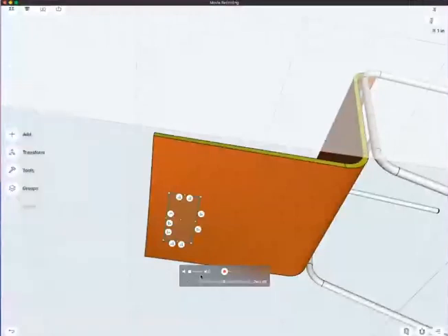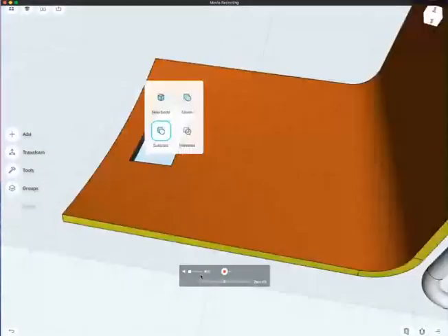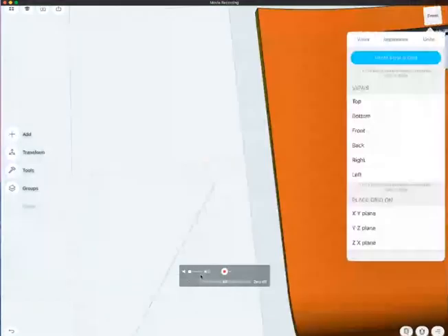Okay, so let's go to tools, and then actually, sorry, not tools. I can just select this face and then with the pencil extrude up, and it creates a cut automatically. See, it's a very smart tool. I can make a new body, I can join it, I can intersect or subtract it. Okay, good, very nice. So let's go back to maybe my top view.